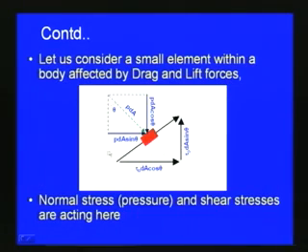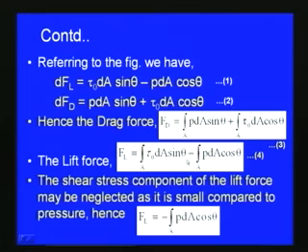You can see that both this force, the P dA sin theta, and the force with respect to the shear stress, are in the same direction. So we can write dFD, the drag force on the elemental area, is equal to P dA sin theta plus tau 0 dA cos theta, as given in equation number 2.